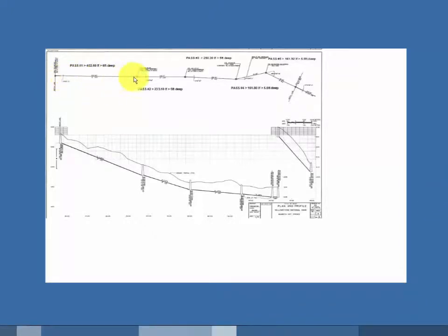The dots on the plan represent manholes, with the distances between the manholes equating to what we will learn as an assembly pass. Previously, you've launched an assembly and you've made a single pass, one set of variables. You've clicked the Add Pass button and then closed your assembly. In this activity, we'll introduce the pass concept, and within the single instance of the assembly, we'll make 5 distinct passes measuring the distance from manhole to manhole to complete the pipeline costing.